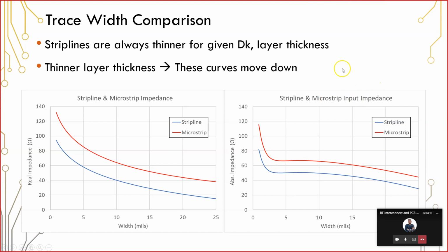So I bring up the input impedance because the input impedance is generally what you're matching to when you determine impedance matching. So when we say impedance matching, this is what I was referring to earlier, where when we're using the system impedance, we want to make sure everything has the same impedance from our transmission line to our vias, to our connectors, to any cables, and then the inputs on any components. So all of those different elements, all 5 of those elements, we would like to make sure that they are matched to the same impedance. So you can adjust the input impedance with the width, but it's the same type of modification that occurs regardless of whether we're working with a strip line or a microstrip.